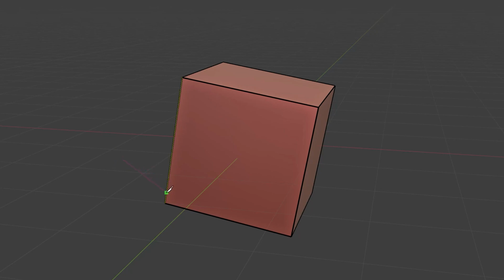You may have noticed that Blender tends to snap to an edge as the mouse pointer comes close to it. We also see snapping if we are forcing Blender to select mid-points on an edge by holding down the Shift key. We may even have snapping switched on by using the snapping icon at the top of the 3D viewport. We can disable all of these snapping options by holding down the Control key as we move the knife.